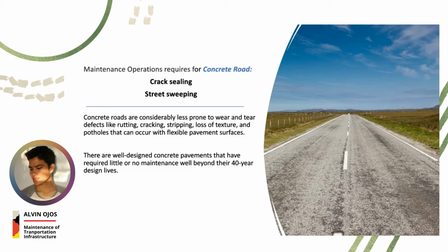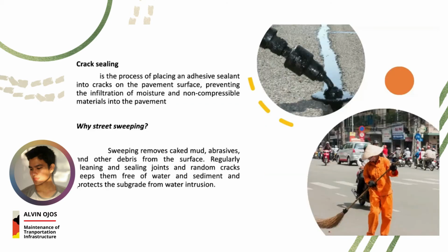So in terms of maintenance, asphalt paved surfaces tend to require more maintenance than concrete. For example, seal coating should be performed every 3 years. There are well-designed concrete pavements that have required little or no maintenance well beyond their 40-year design lives.